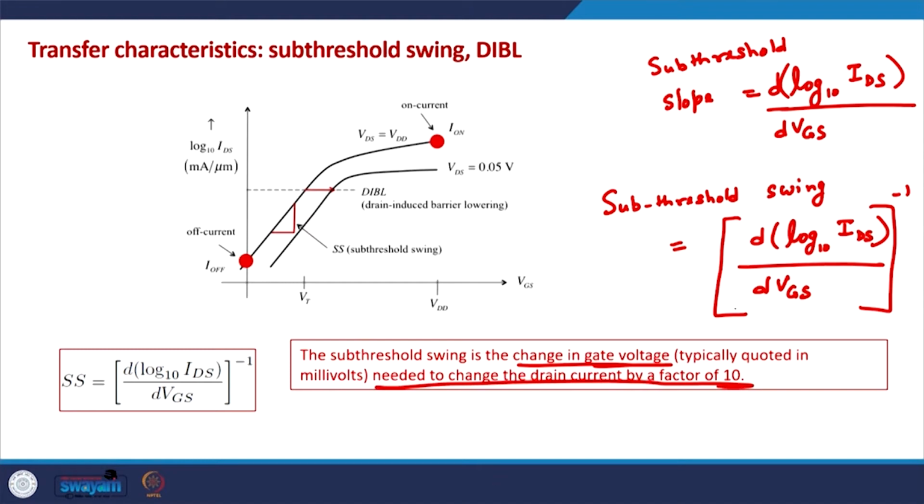Ideally this sub-threshold swing would be dVGS divided by d log IDS, but that is not the way to understand it, because VGS is the independent parameter and IDS is the dependent parameter. So we write it in this way, we do not write it the other way.